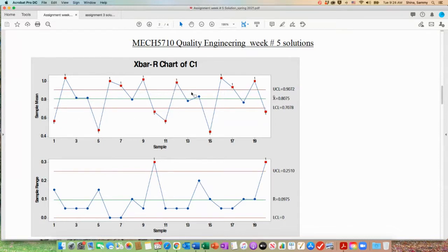Now, the control limits are calculated from day one. Right now in the example, we're calculating them as we go along. So every time we have a red mark, it's either lower than the lower control limit or higher than the upper control limit. Just to tell you that control chart A is a chart of sample averages, which is always normal no matter what the population is.